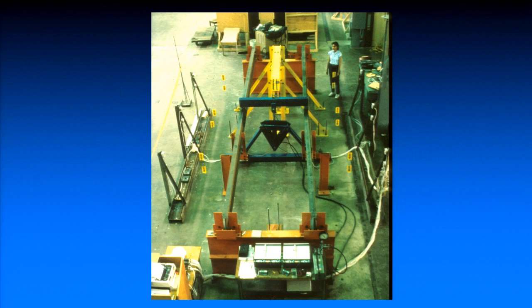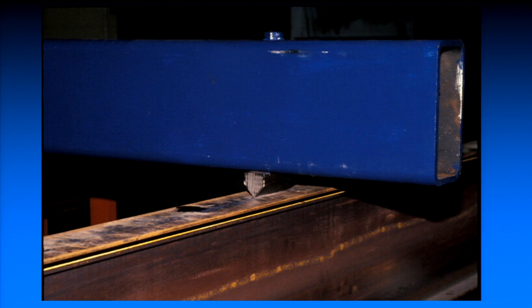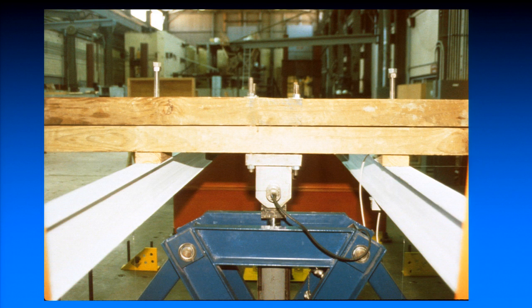In the laboratory, quite frequently, this shows some buckling tests, and this is a fancy apparatus we call a gravity load simulator. It simulates gravity load, and it doesn't provide any lateral restraint. It allows the load point to be able to buckle and not really impact the behavior. Usually when we do this through our loading system, we'll go out and have fixtures machined to a knife edge. We have them heat treated so they don't dull. What we want to do here is simulate a point load where that beam can twist about that knife edge and it doesn't really impact the behavior. To give you a feel for things, on a test like this, if I get a certain buckling capacity, we did some other tests just throwing a 2x4 in there instead of the knife edge, and it doubles the buckling capacity. It's very substantial. Tipping restraint can be very, very significant.